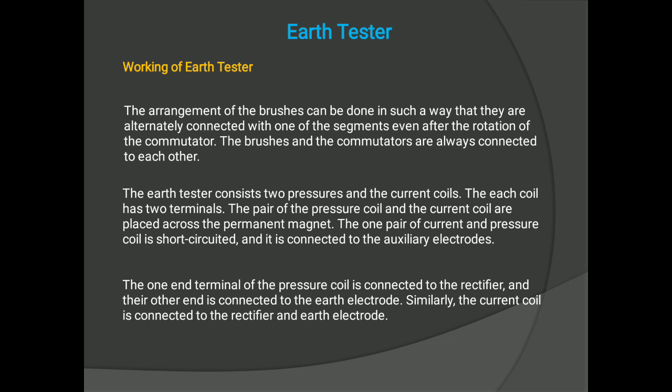Although the instrument is immune to stray currents, while taking readings, sometimes you will observe that the needle vibrates. This happens only at the instant when the stray alternating current has the same frequency as the frequency generated. For such occasions, either increase the speed of the generator a little or lower its speed.